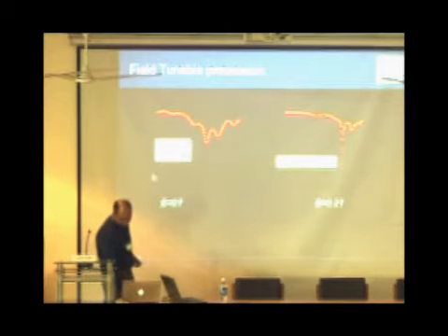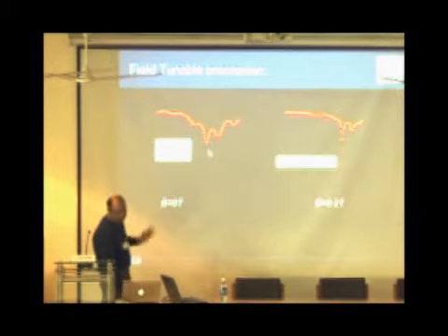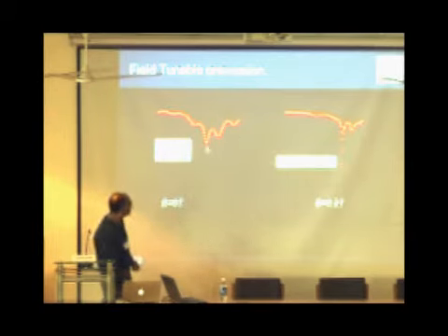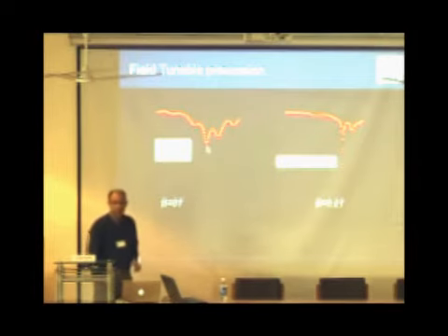So this is essentially from 8 to 20 gigahertz, this scale, and what you can do is you can measure the return loss at different frequencies of any wave that you launch in the transmission line. And essentially if you apply an external field, a DC bias field, you can shift the return loss where you get the maximum return loss.